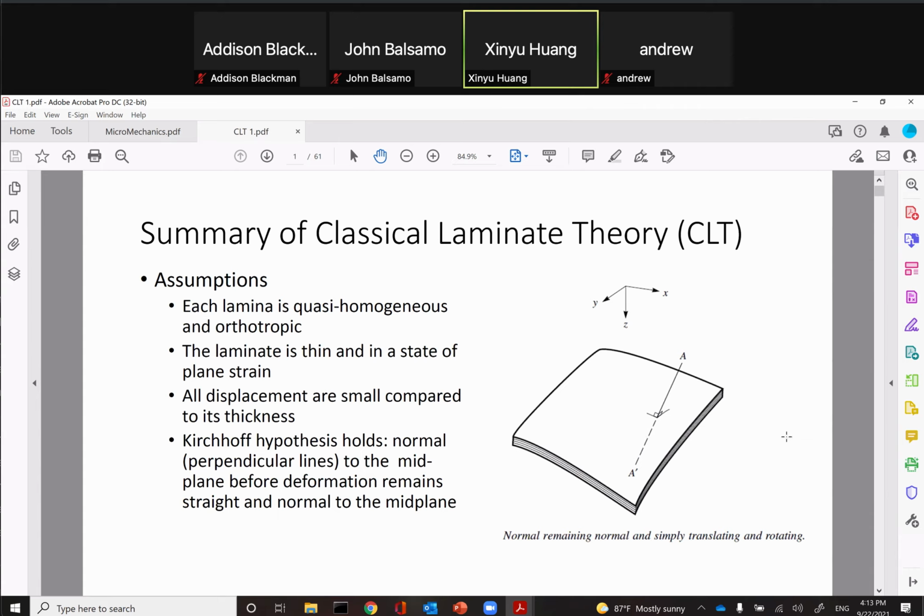Okay. Now for plate theory, it's more complicated. For beam theory, there's only one way you bend it. You have a perpendicular line. This is a neutral axis. They remain perpendicular, they remain plane. That's the two assumptions. Now in plate theory, you imagine the whole plane, everywhere you can draw, there's a midplane somewhere, everywhere you can draw a perpendicular line to it, right? And you can imagine that when the plate bends, this perpendicular line also, everywhere it moves a little bit, right? But at the location where that intersects this midplane, that perpendicular condition remains.